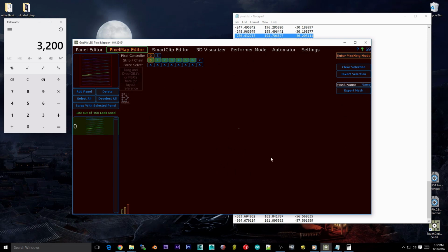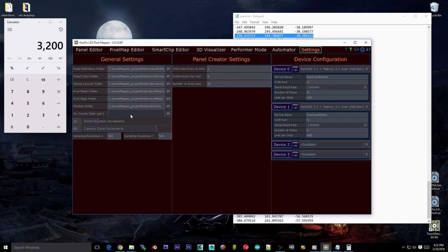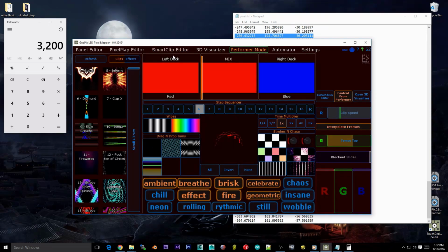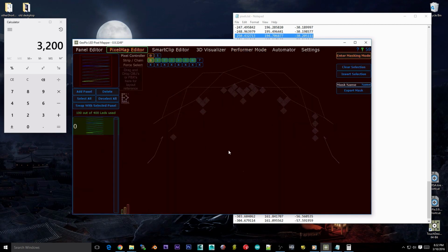And as LED communication goes, you have to have these inside your data packet so that your other LEDs are in the right place in terms of the byte order and all that stuff. So this is also inherently part of the preview. When you create a viz table, it's really important to realize that you have to include all the dummy pixels that you are not necessarily mapping. So here we have, again, 100 pixels. You need to have 101 to 400 mapped out. They can be anything, it doesn't matter, because you won't really see them. Well, actually, you will see them in the visualizer. You need to have them just be 0, 0, 0.